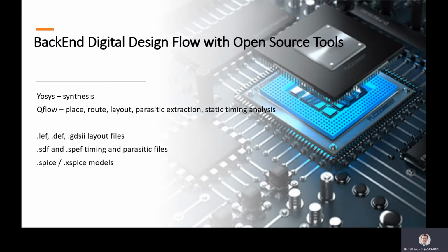The second important class of files relate to the timing parameters of the post layout design. So you can find the timing parameters of gates and gate paths in the .sdf file, and the parasitic resistance and capacitance will be located in the .spef file. We will go through the .sdf and .spef files in greater detail in a future session.